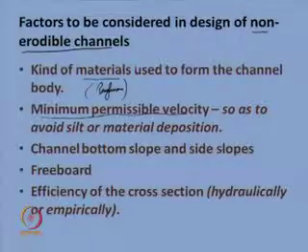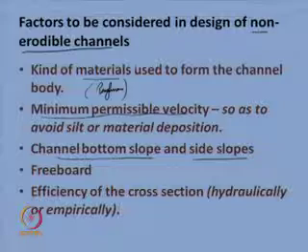This is to avoid any suspended materials, if at all they are there, and also to avoid growth of aquatic plants. Then another factor that is quite important in designing non-erodible channels is the channel bottom slope and the channel side slope.